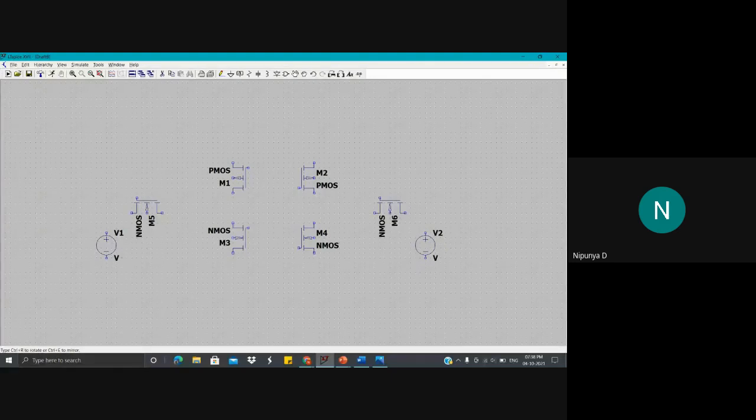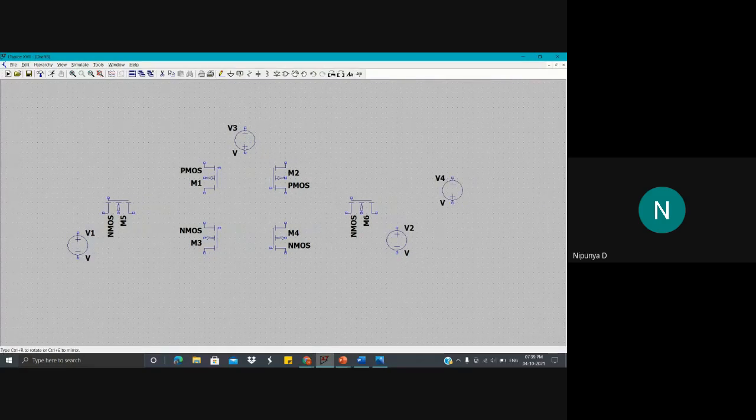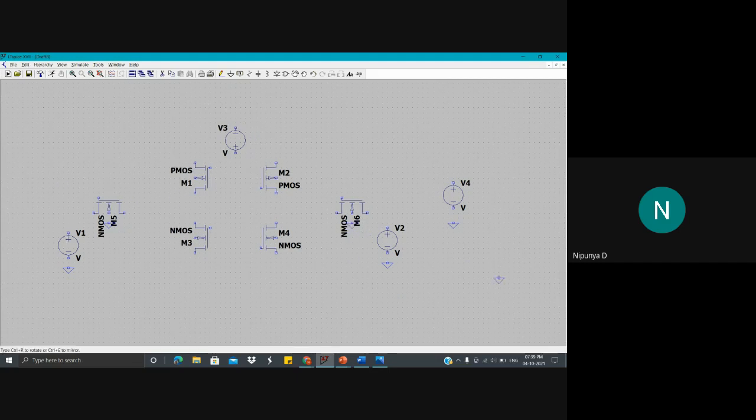We will be requiring one each for both the bitline and the bitline bar, one for the VDD, and one for the word line. You can place these at any point, so that we can connect them by adding labels. Then we have to use the grounds. For the transistors which form the latch element, we will be connecting across, whereas in these two access transistors the gate is grounded. So make sure that you add ground to both of these access transistors.